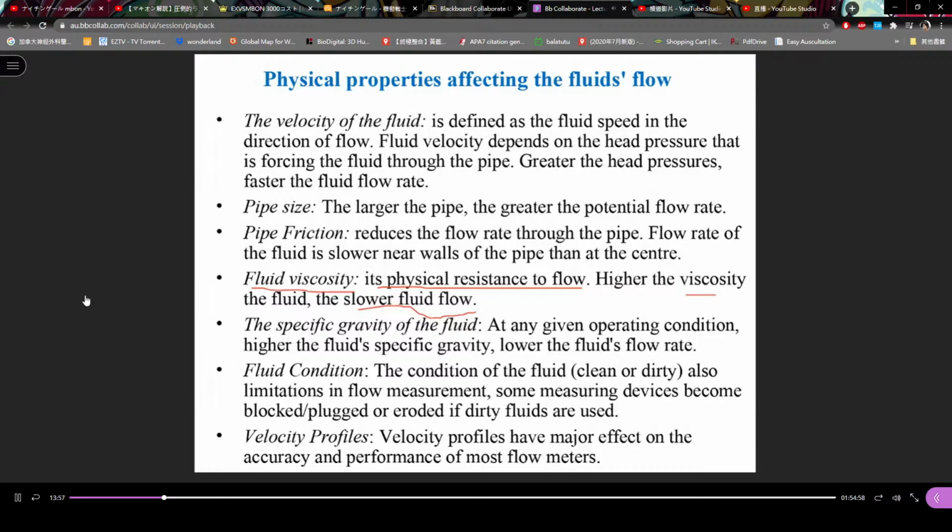We have to heat it to reduce the viscosity. When the temperature is higher, the viscosity is lower. So, say after a few kilometers, a boiler must be used to heat the pipeline, so that the viscosity is less.